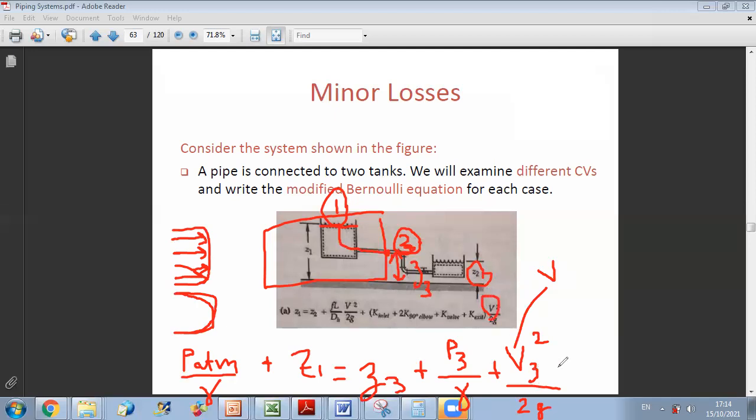And so already you can verify, when you get the value of V from the previous step, that your flow is turbulent. No need to assume, because you have already done this step. So you calculated V and you have Reynolds. If Reynolds is larger than 2100, then you have a turbulent flow and your profile is like this. So V at the center line, V3, can be approximated by V average.